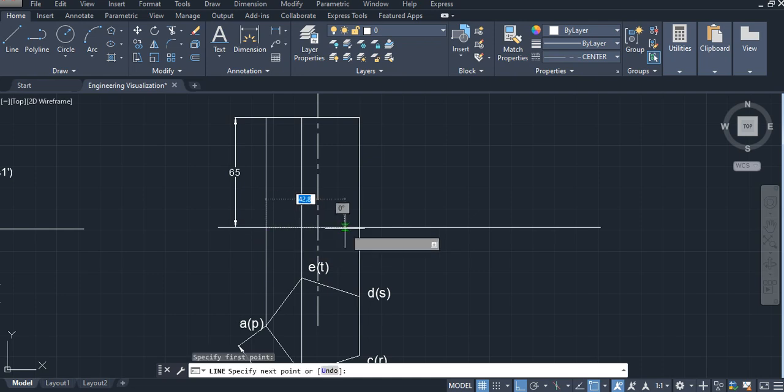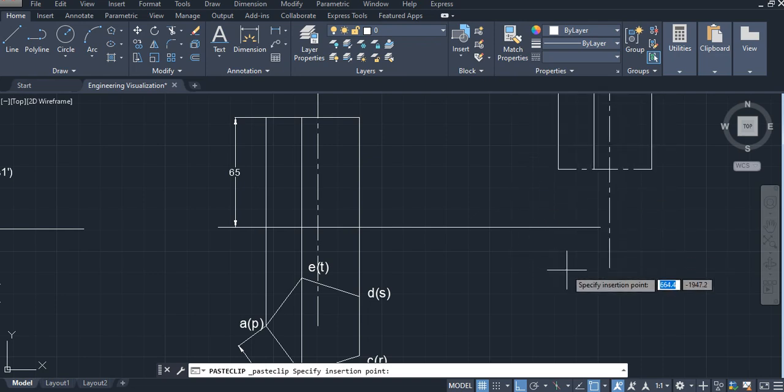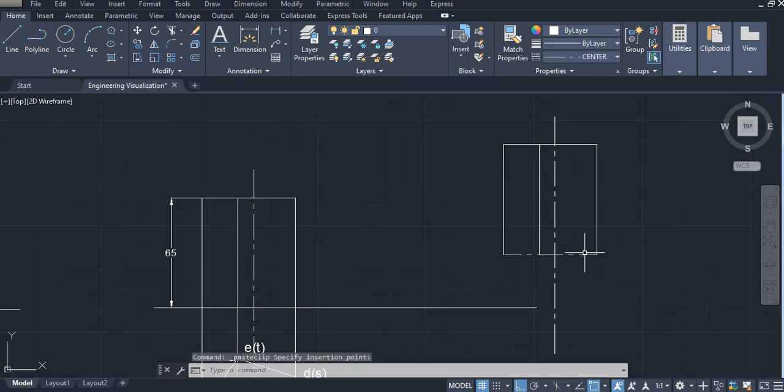So we need to draw a baseline here of the pentagon. So we need to move this vertical object from here to here with the axis inclined at 45 degrees. For that, you just select all the lines, with the base side also and the axis line also. You just copy with Control C and paste here with Control V. So we have an object here.